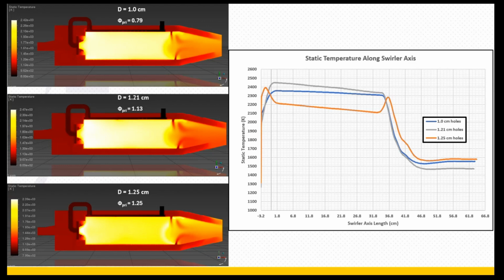And that's one of the things with pure ammonia combustion that you want to avoid, because what typically happens is that if your flame reignites, your NOx emissions typically jump back up, so you get a net increase in NOx emissions because you still have ammonia fuel that survives, and now it's burning in a more lean environment when it gets to the dilution holes, so you want to avoid that. So that's enough for that one.